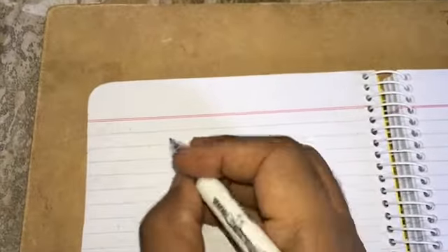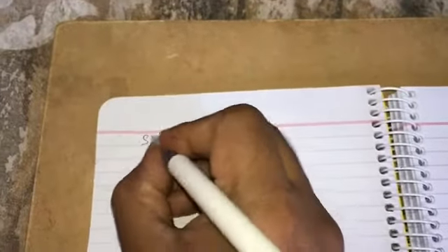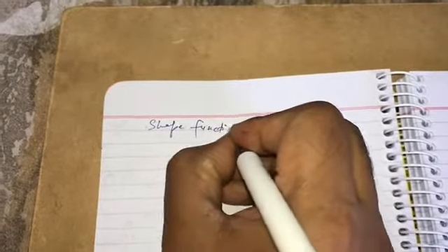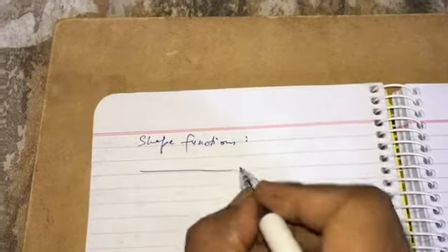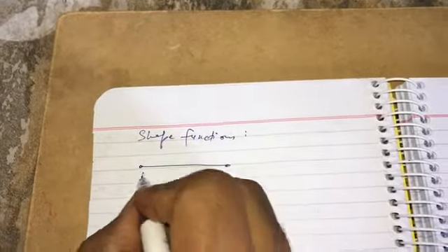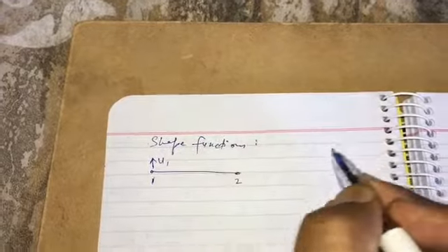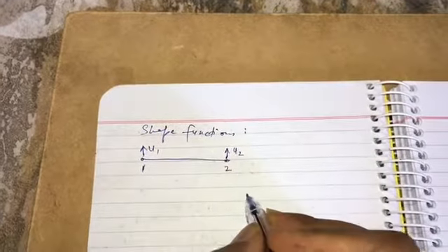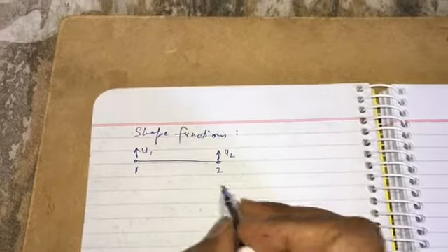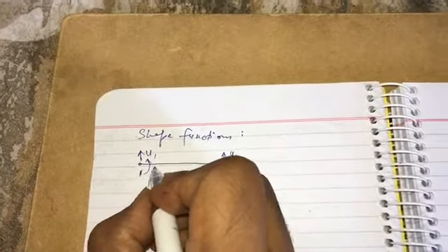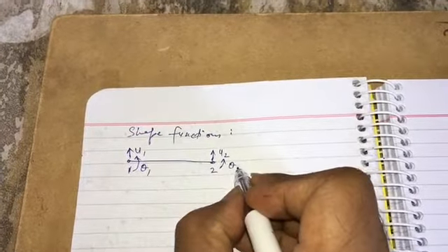Now once we have the weak form, the next step is to solve the problem. So in order to solve the problem, we have to know the shape functions. So we have to see the degrees of freedom first. As we have seen earlier, if there are two nodes, 1 and 2, each node will have 2 degrees of freedom. So one is u1, this is u2. These are displacement degrees of freedom, and there is theta. So this is theta 1 and theta 2. So theta is the slope.